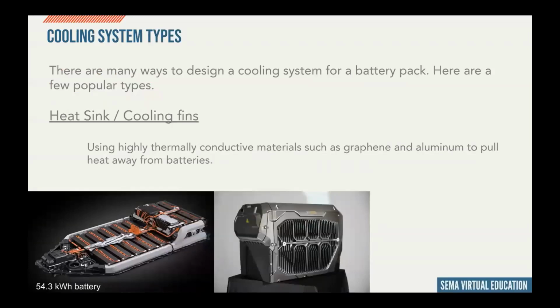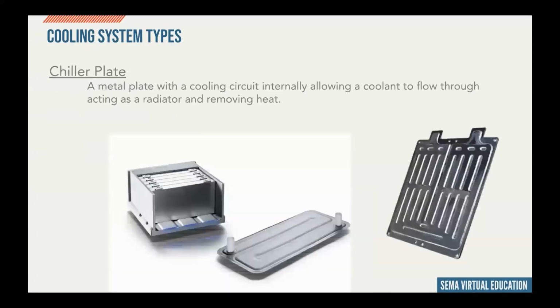So in passive systems, they're typically heat sinked or cooling fins. There are some very high performance applications, including something Lexus is doing, where they are air cooled in high performance. So they're able to remove a significant amount of heat through air cooling. But typically we see motorcycle or lower voltage applications with cooling fins to pull the heat away from the cells and discharge it out into the air.